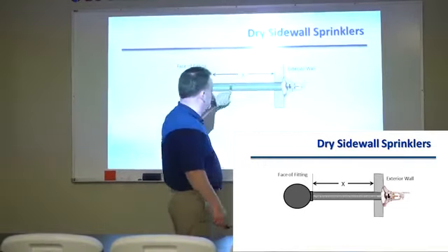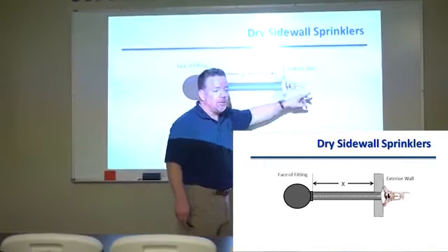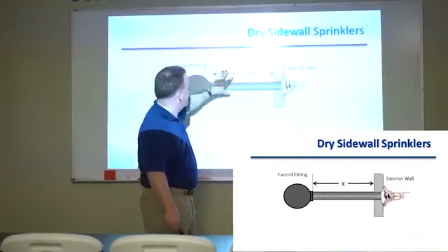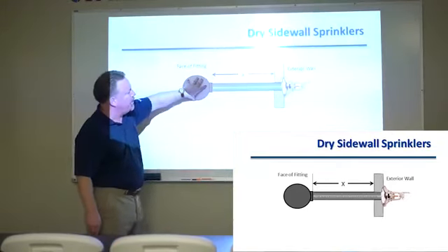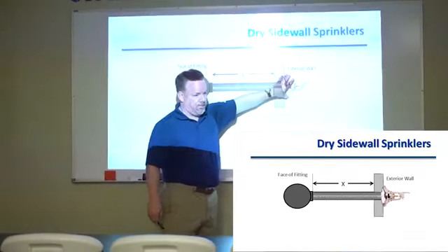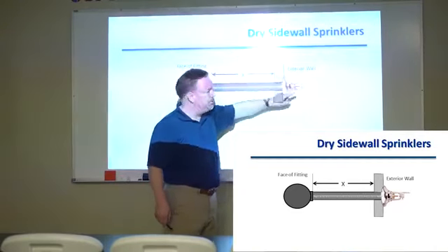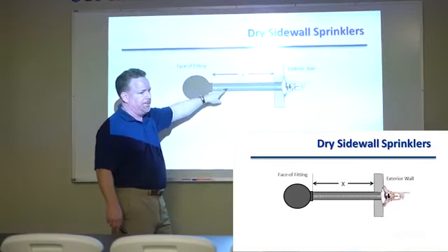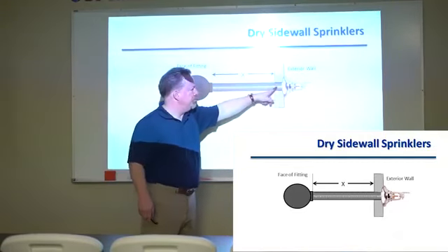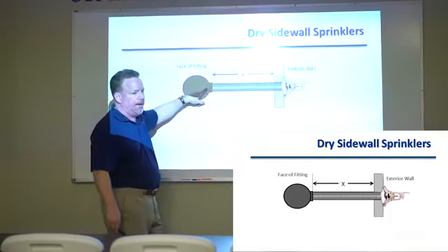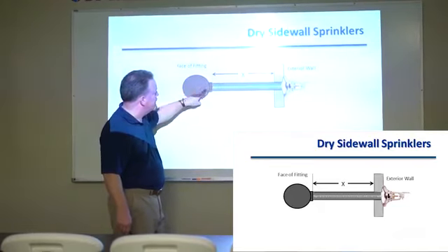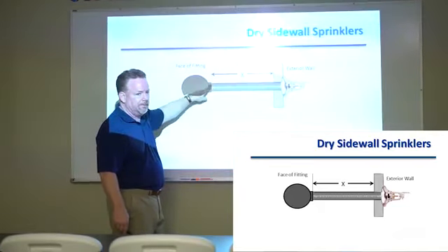You have this arrangement. One of the things we're concerned with, though, is if this water pipe is not far enough away from the frozen area or the unheated area or the cooled space, you'll get creep of the cool temperature. This will conduct all along that pipe, and if it's too close, it'll create an ice plug right there.